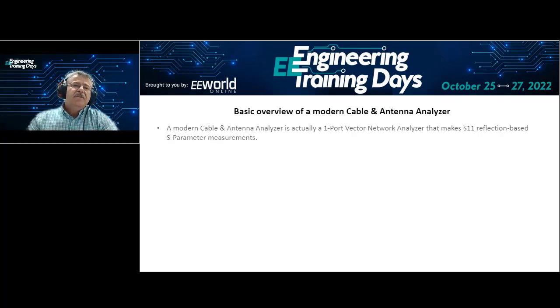So let's talk about this for a second. It may not be apparent to some people, but a modern cable and antenna analyzer is really a vector network analyzer. It's a one-port vector network analyzer that uses vector error correction. That's what the calibration is. And it makes an S11 reflection-based S parameter measurement. Now, we create this GUI on these products that simplifies the use for the field technician, and we'll talk a little bit about that.